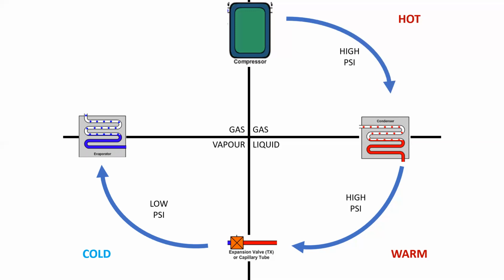And that's because this extremely cold vapor is going to pick up BTUs of heat energy that are in the room that we want to cool. And in doing that, picking up the heat energy, it will evaporate. Evaporation, evaporator. At this point, it's now a cool, low pressure gas. And it goes into the compressor to be recompressed up to a high pressure, and the cycle continues.